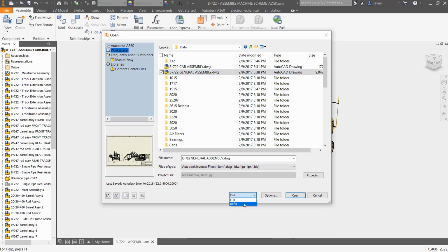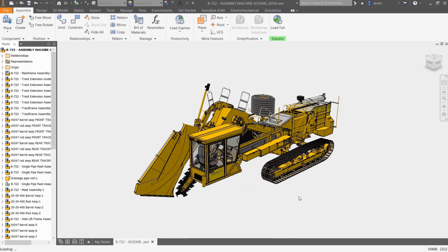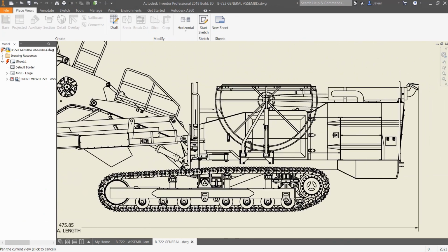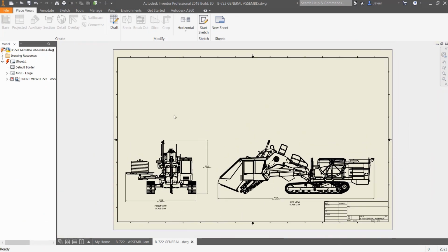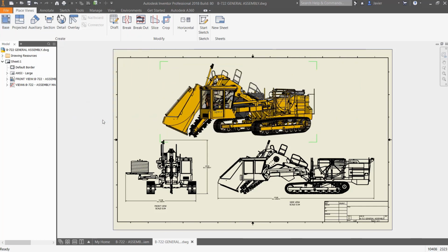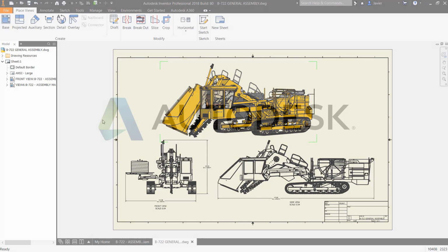All of your designs can benefit from these improvements, but nowhere is this more evident than with large assemblies. To further improve performance of large assemblies within drawings, updates can be deferred with the new context menu, so that users control when changes are reflected in the drawing. And users can turn off the preview drawing view creation to conserve graphic resources. Autodesk Inventor removes barriers normally associated with complex designs by delivering the most effective 3D modeling tools available in Inventor 2018.